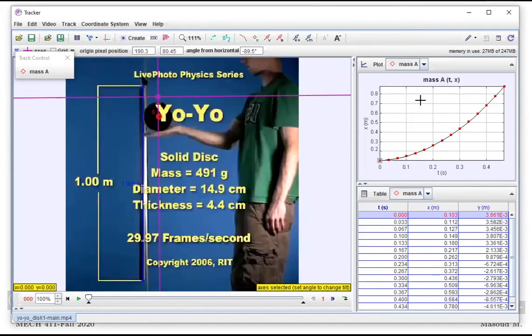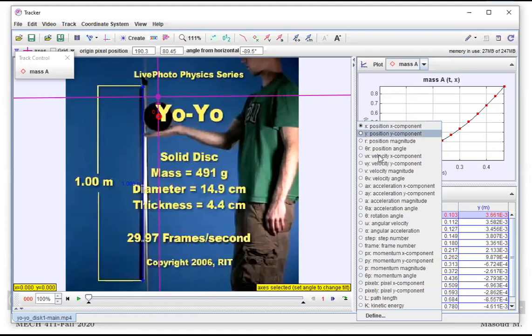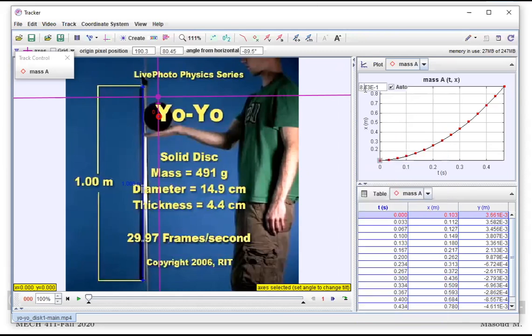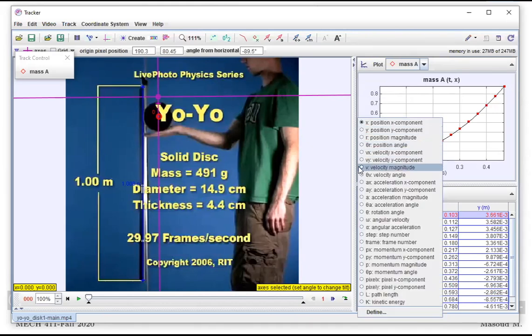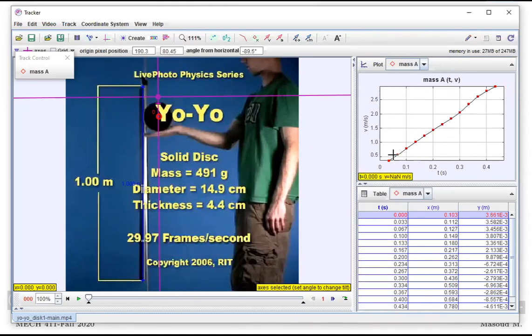The last thing I want to mention is that quickly, so this, as you realize that this tells you what position you're interested, X, Y, Z, rotation, angular velocity, angular displacement. You can even get velocity from here. If you go there and you go to velocity magnitude, so almost increasing with the same slope, which is what we expect, right? This yo-yo is falling down, so the velocity is increasing because acceleration is constant, is acceleration due to gravity. So the velocity is increasing with a constant rate.